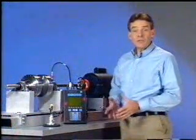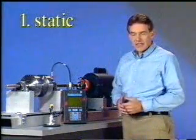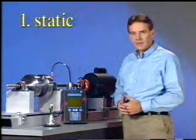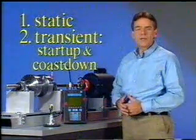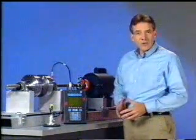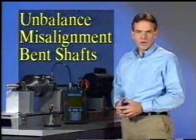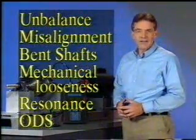Phase analysis can be used for two specific operating conditions. One is a static condition. That is, the machine is operating in a steady state with only small fluctuations in speed and load. The other is a transient condition. That is, the machine is changing in either speed or load. The most common transient application is during a startup or coast down. But here, we will use static phase measurements to diagnose machinery conditions such as unbalance, misalignment, bent shafts and cocked bearings, mechanical looseness, resonance, as well as a brief overview of operating deflection shapes.